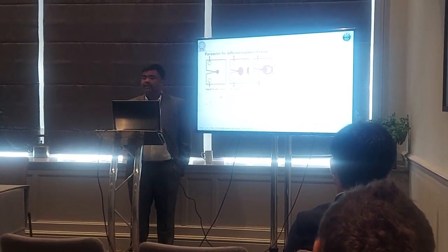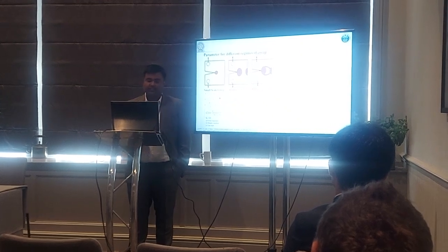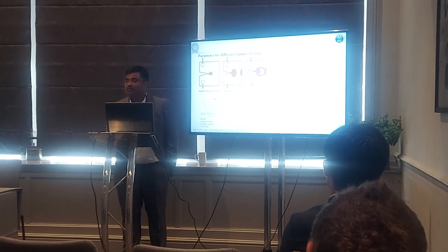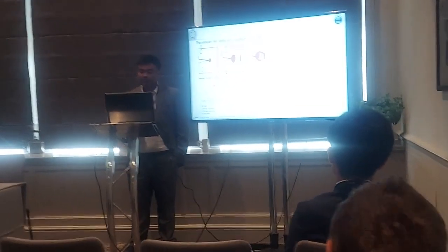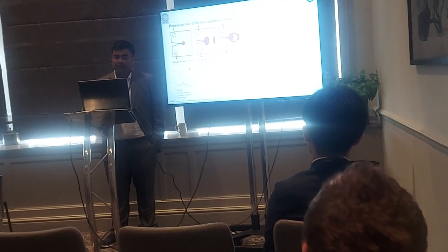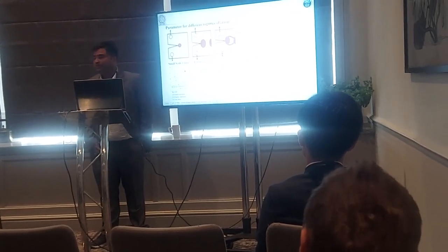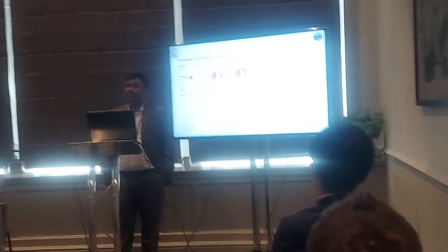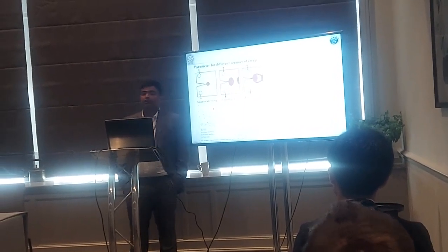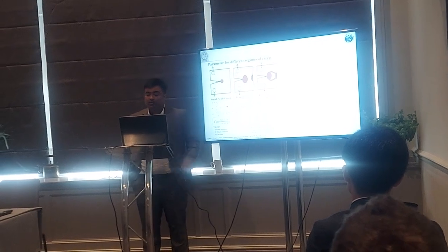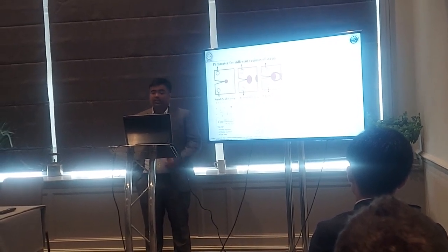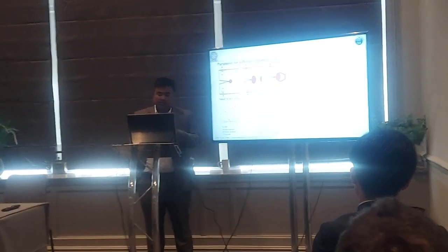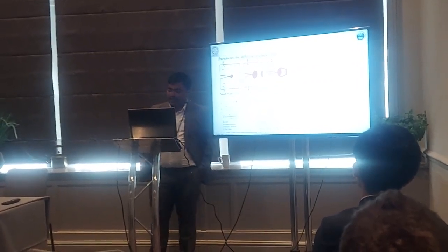So Riddle and Rice proposed this equation for the CT integral, which was famous for some time. After that there is a problem, because this depends on the creep exponent's values, and it cannot be found experimentally. Theoretically we can find it with the help of this expression, and after that Saxena gave this expression to characterize small scale creep and transition creep by experimental calculation. So this expression is used for this.